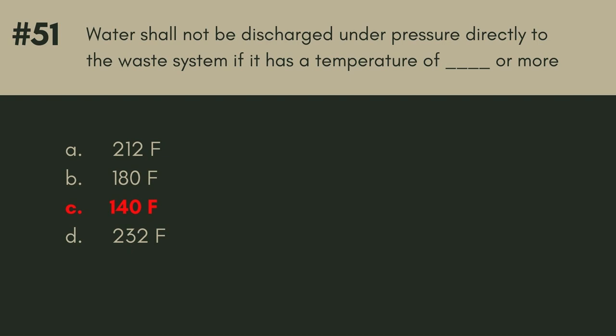140 degrees Fahrenheit. Water shall not be discharged under pressure directly to the waste system if it has a temperature of 140 degrees Fahrenheit or more.